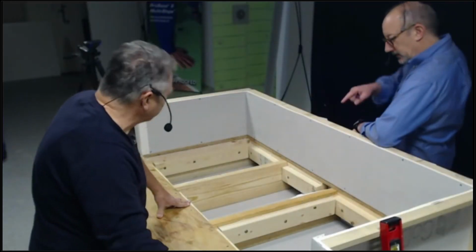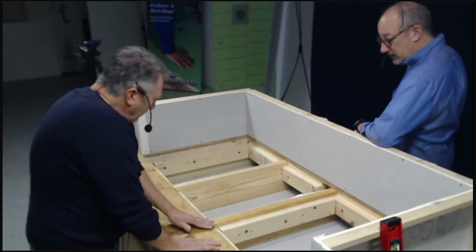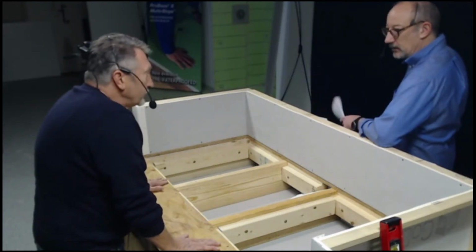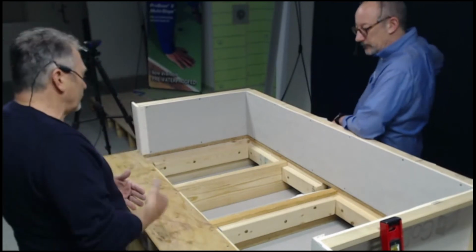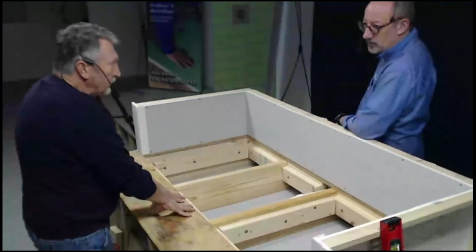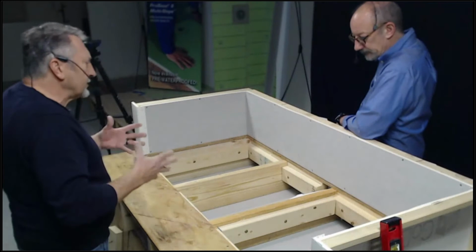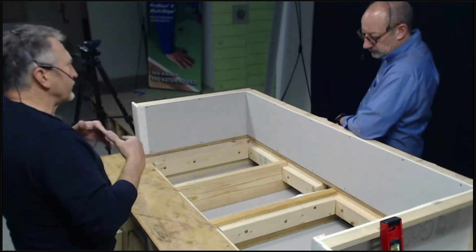I imagine you could do that with a nail gun. Nail gun, sure. Yep. So that leading edge is really just supporting that cut edge of plywood, so that if you stand there, you don't get any kind of deflection or weight. Right, because then you could get cracked grout lines, cracked tile. Yeah, it's almost like cross blocking. Exactly. At the end of the day, you want to make sure that the substrate is structurally sound.